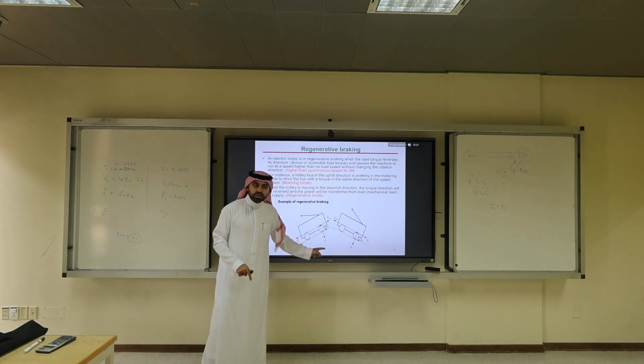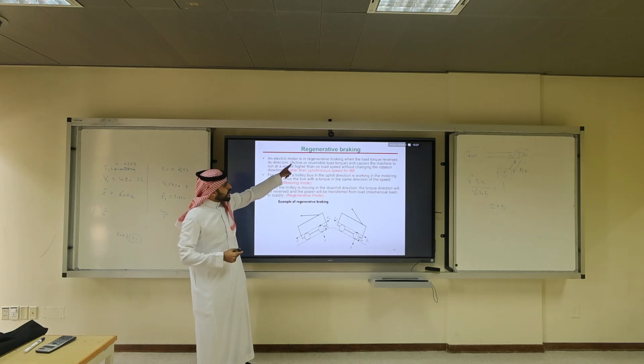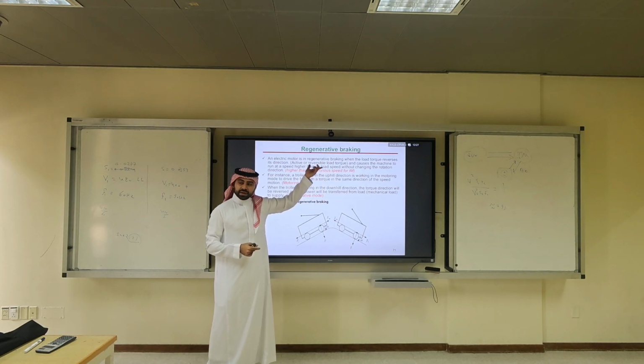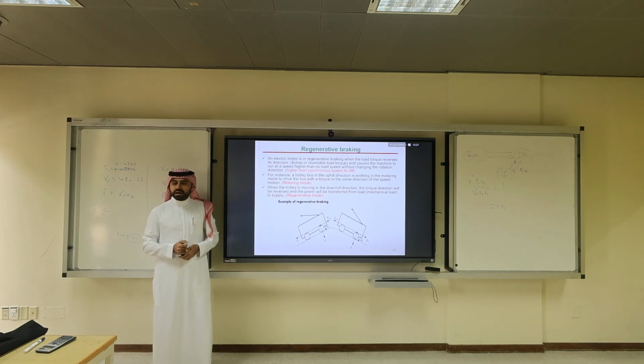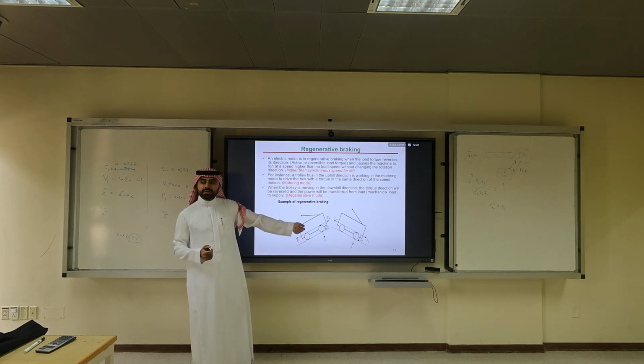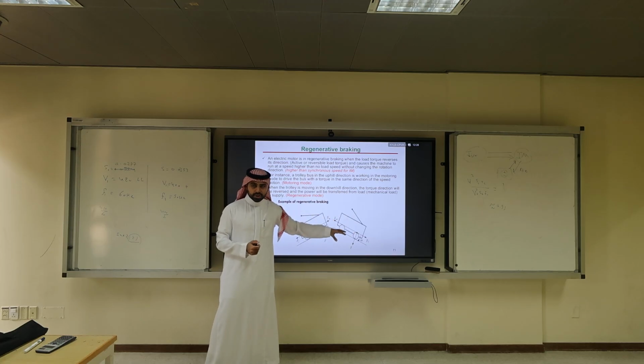So is this a constant torque? No. It's a torque that varies with the speed. Is it an active or reversible load torque? Yes. Is it dynamic? Think with me. What is meant by dynamic? Dynamic means it is capable of changing its torque depending on the speed, or depending on the position of your trajectory. Is it dynamic? Yes.